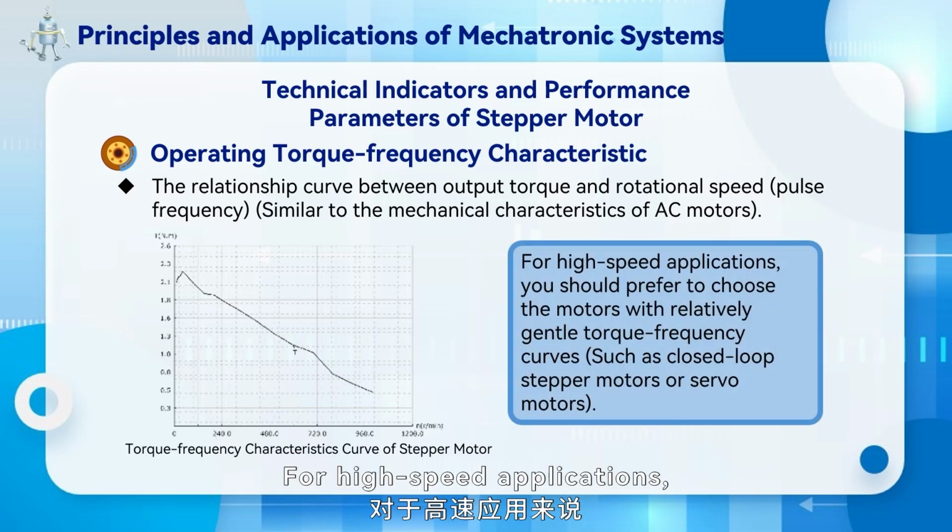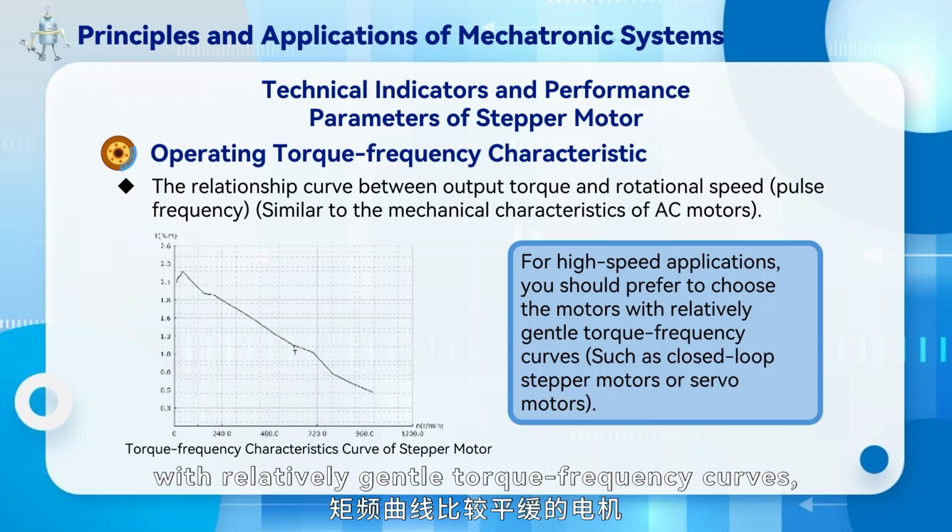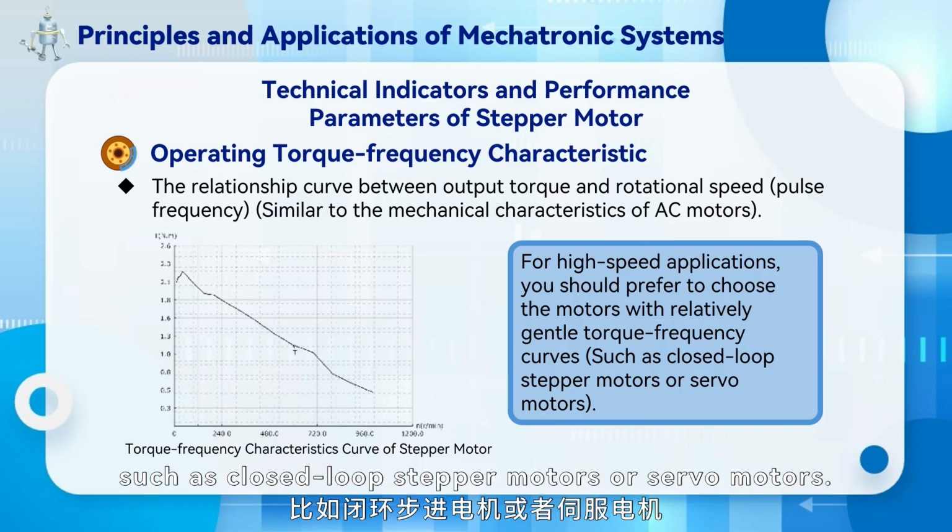For high-speed applications, you should prefer to choose the motors with relatively gentle torque frequency curves, such as closed-loop stepper motors or servo motors.